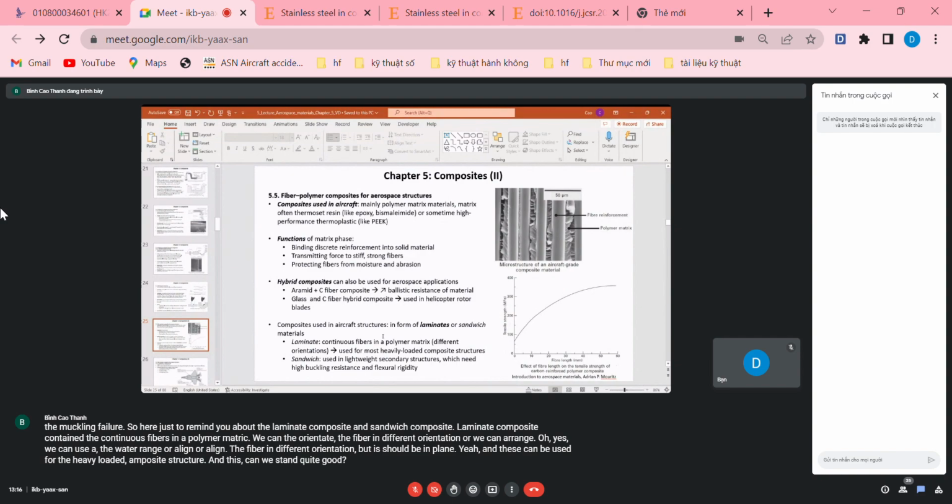And this can withstand quite well the force oriented along the direction of the fiber, but in other directions, we cannot withstand as well as in the direction that we have mentioned. That's an issue of composite materials reinforced with fibers, because only in the directions that we reinforce with the fiber can the material withstand good load. Otherwise, no.